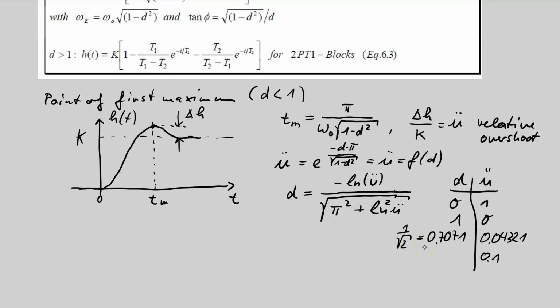In the student paper, you can read on page 59. This is a damping factor of 0.591. If you want to have only 1% overshoot, the damping must be a little bit larger, then the damping factor is 0.826. Okay, so far the step response has another property, also displayed in a graphical diagram in my workbook.